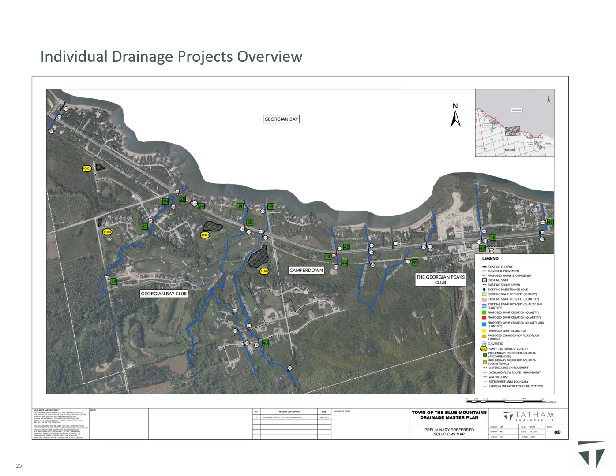Expanding existing floodplain storage areas upstream of culvert crossings to provide attenuation of flood peak flows was considered in accordance with Alternative 2C. Under this alternative, 5 potential floodplain expansion projects were considered, and following the individual project evaluation, none of the floodplain expansion projects were recommended for inclusion in the preliminary preferred solution. These projects would face additional challenges of potential environmental impacts and complying with the MNRF Floodplain Management Technical Guidelines.